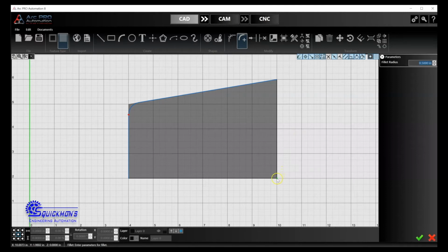I'm going to click on the corner first. And notice the same thing on the fillet tool as... oh, we're already clicking a corner. It's up here. So let me click escape a few times. So I'm going to click fillet tool, and I'll click this lower corner, and it rounds it. So I have a few options here. I can either designate a radius by giving it a call out up here, 0.375. If I click in this black area, it's going to give me a preview on the screen.